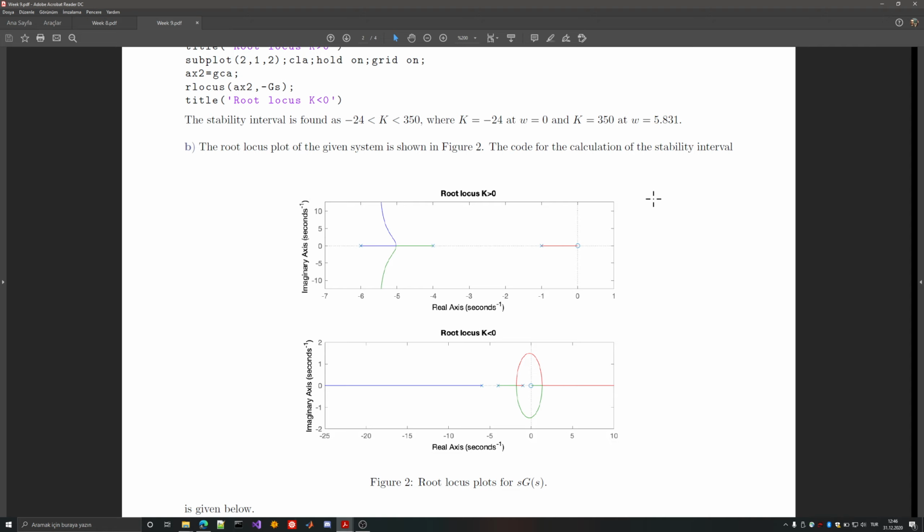And since all three poles will stay on the left half plane, I will have no stability issue on the positive side. So if I have a positive p-type controller, I can choose whatever I want as gain. It will be stable. Of course, I'm not going to choose any controller, because I might have time specifications or some considerations for the closed loop, some objectives, but the whole positive interval is available for me as a controller that stabilizes the system.